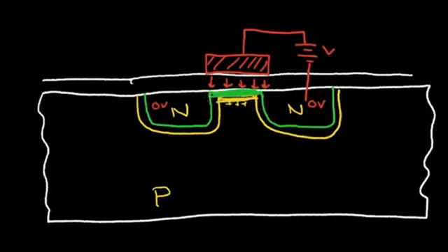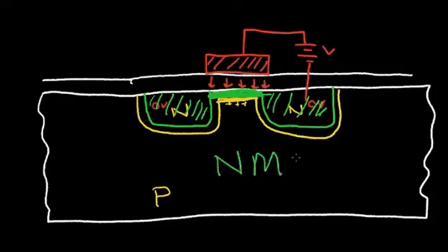So when this junction, or when this region inverts and becomes an N-type region, I now have conduction. I have a conduction path from this region to this region over here through the region underneath the gate electrode. So again, this is an NMOS transistor. And we'll talk more about this in future videos, but I just wanted to give you an overview of how important this depletion region is, and that it's important for a diode, it'll be important for a bipolar transistor, and it's important for MOSFETs.